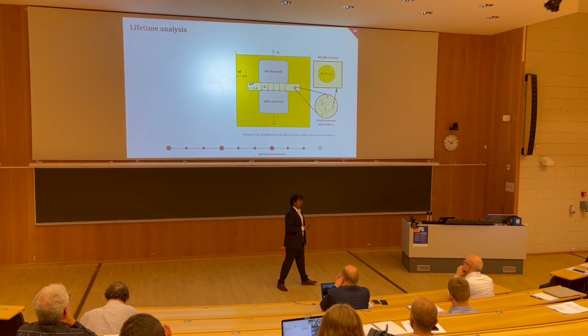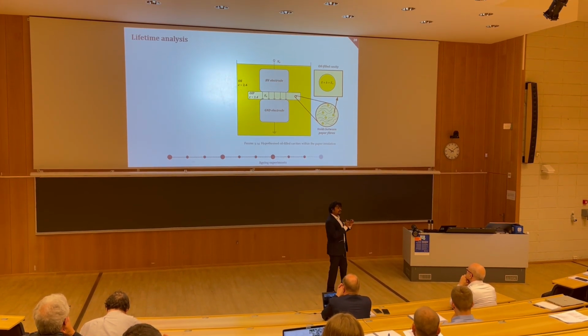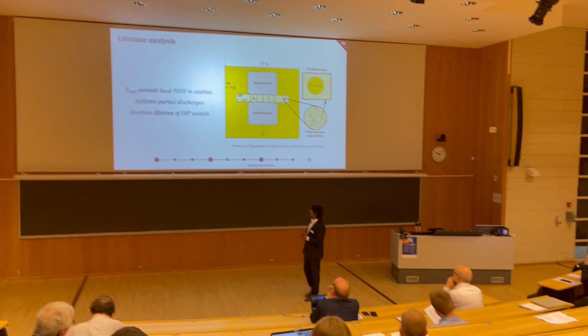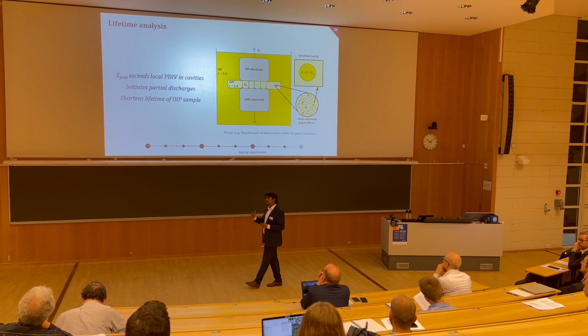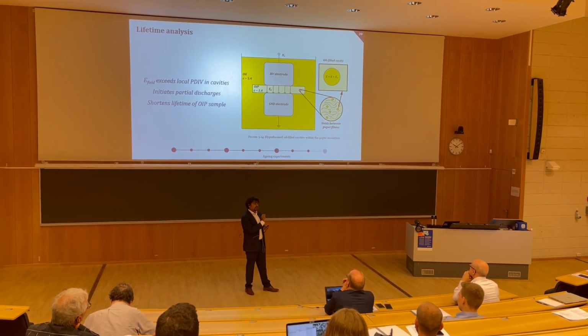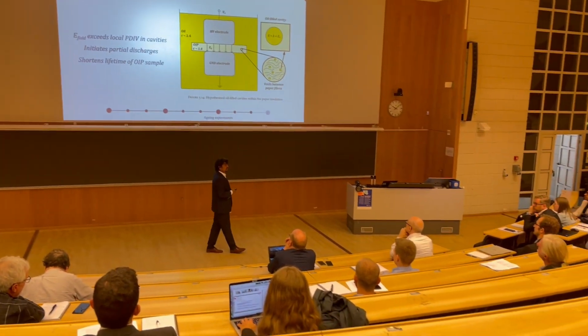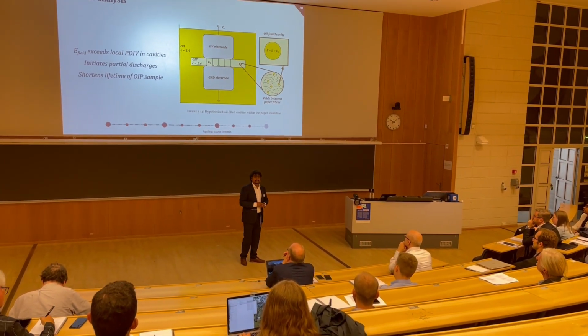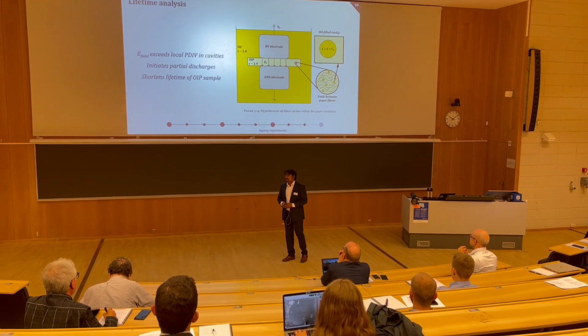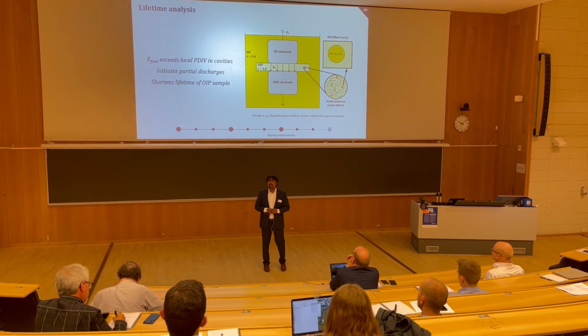The next hypothesis that we had was that there are oil-filled cavities inside the insulation samples. And what happens is that when the E field exceeds the local partial discharge inception voltage of these cavities, it initiates partial discharges and thereby shortens the lifetime of samples. However, this needs to be verified, but this seems the most likely cause.